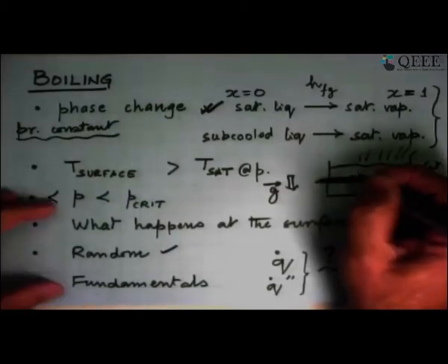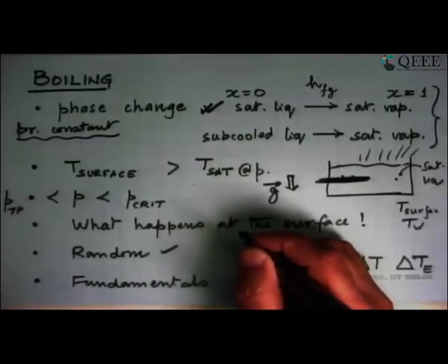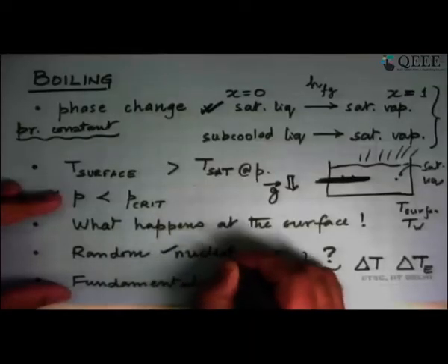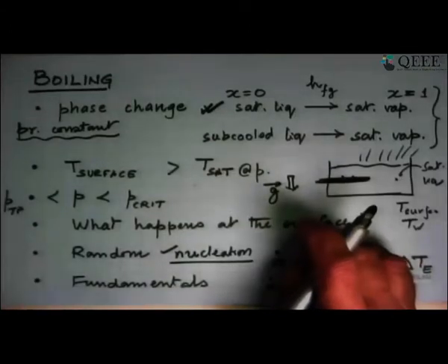There are also times that if you look at another point, this may not be happening. If you are boiling water in a pot, you will see that bubbles originate at certain points inside the vessel and not everywhere. Those points where the bubbles are originating are what we call nucleation sites, and not the entire surface is covered with nucleation sites.